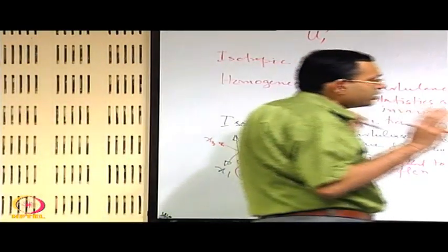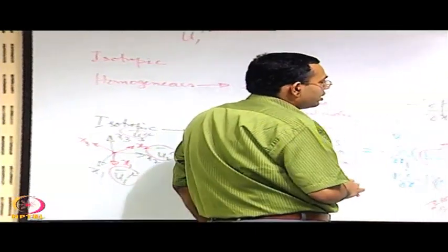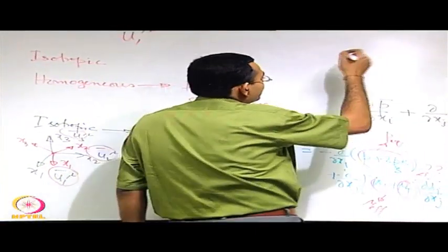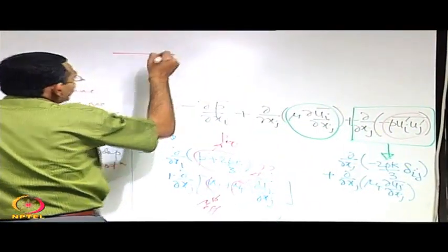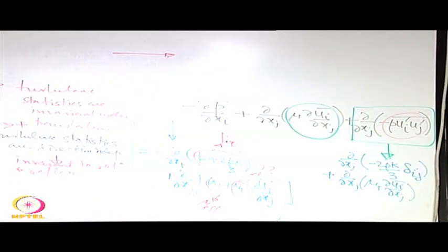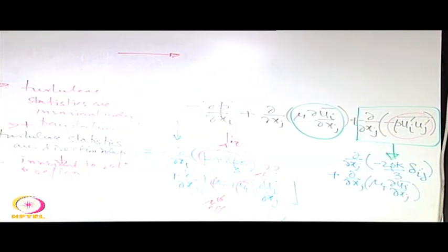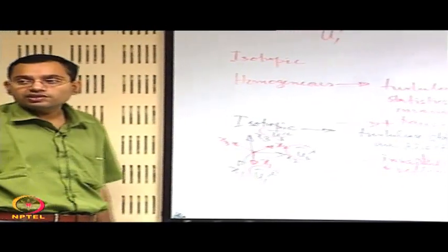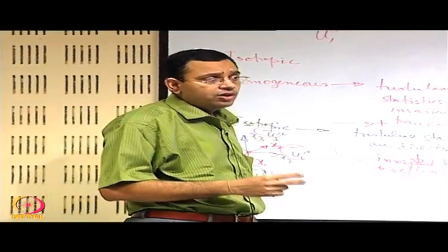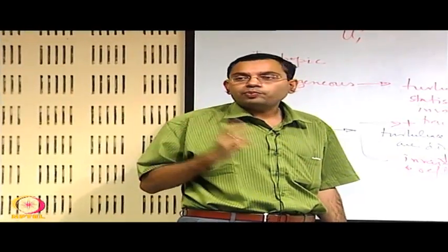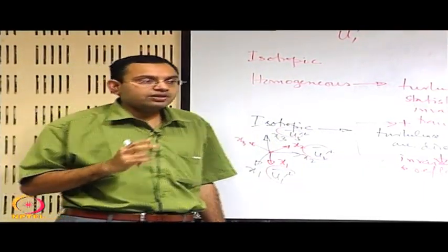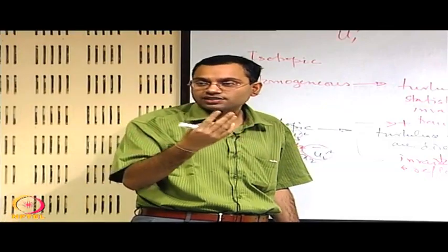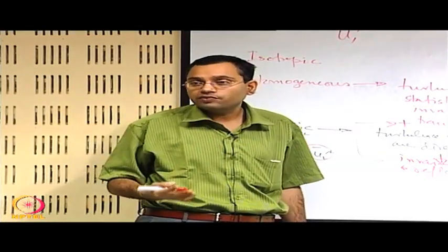So with this understanding of isotropy and anisotropy, now we will consider how these ui prime uj prime terms are coming. Let us say we want to describe this with an analogy of the origin of shear stress that we discussed when we were talking about viscosity in one of our earlier lectures. If you recall, we introduced two important physical origins of viscosity. One is the transfer of molecular momentum between different fluid layers, and the other is intermolecular forces of interaction.